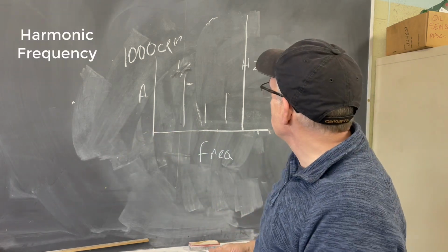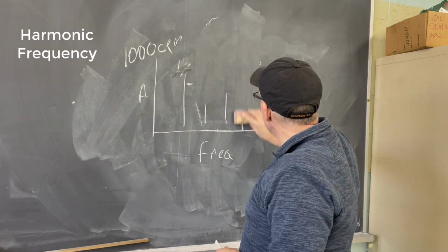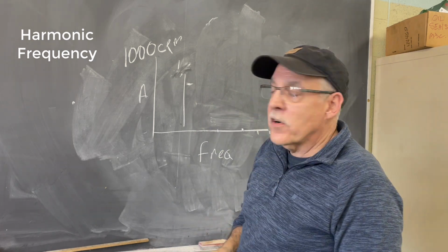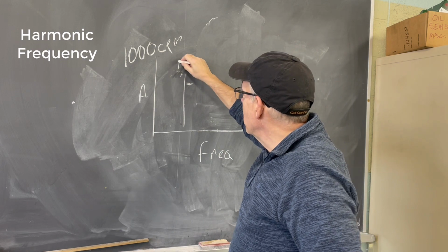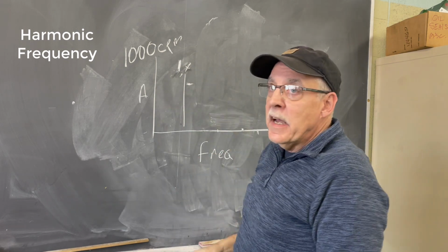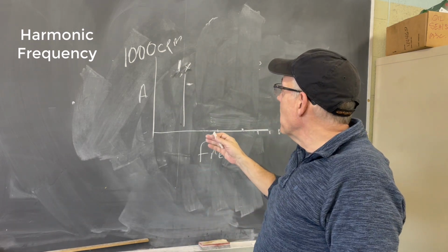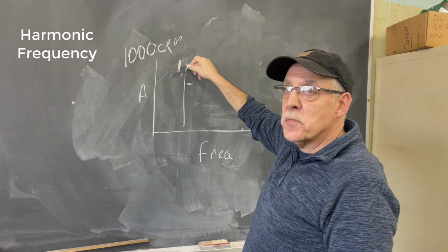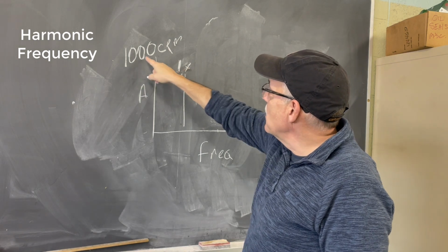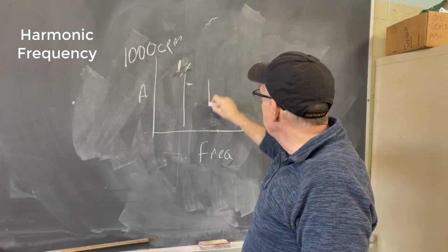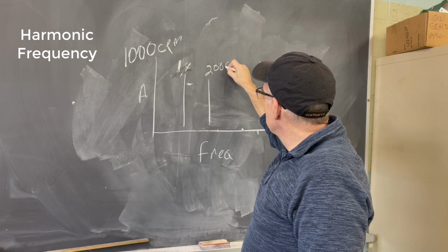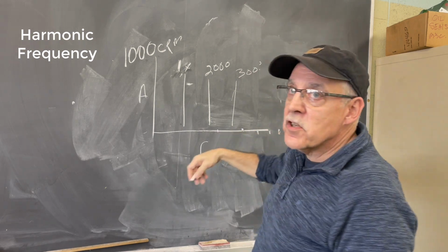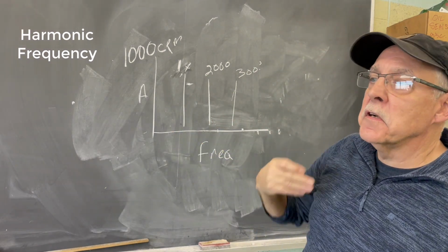So a harmonic is just that you have the fundamental frequency. So let's say for looseness, okay? The fundamental frequency for looseness might be a multiple of 1 times. And then when they would have harmonics, would be just other peaks that are exact multiples of that first peak. So a harmonic of this at 1 times, we're at 1,000 CPM, harmonic would be 2,000, 3,000,